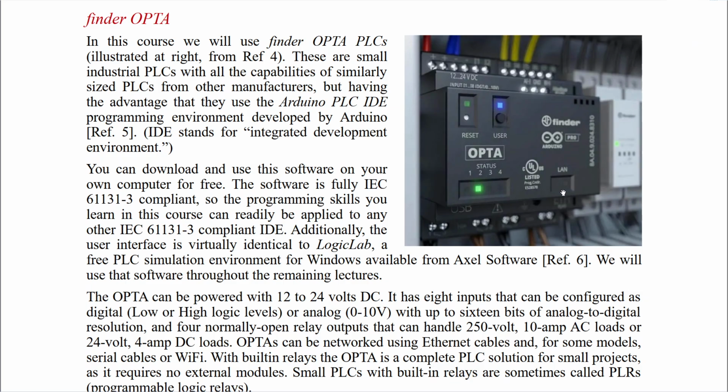It has a full programming environment, which is provided by Arduino, which is free to use and is fully IEC 61131-3 compliant. So all of the programming skills you'll learn on the Finder Opta can be transferred over to any other more commercial type of PLC system. Sometimes people will call a small package like this, which has integrated inputs and relay outputs, a programmable logic relay, PLR, but we'll just call it a PLC because as far as programming is concerned, it's identical to any PLC.